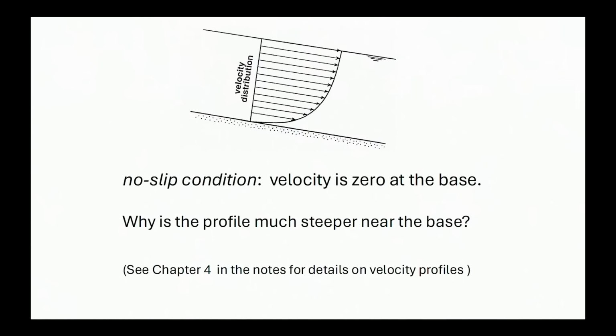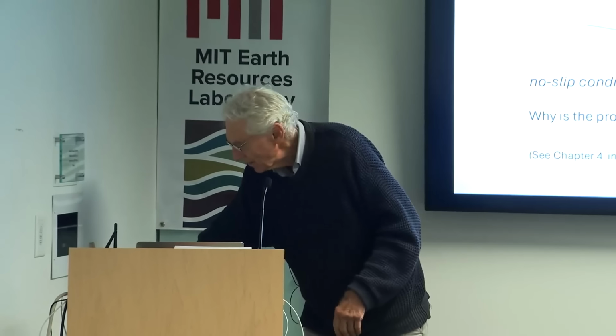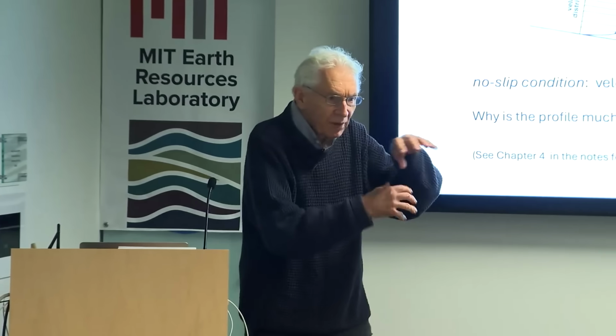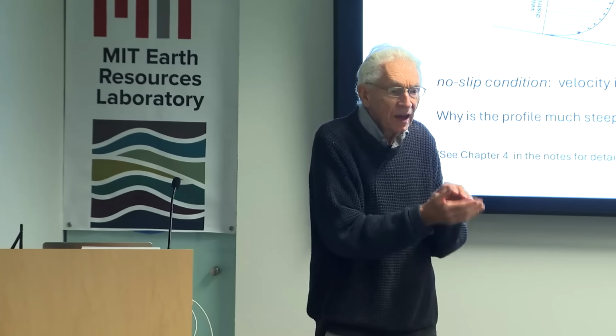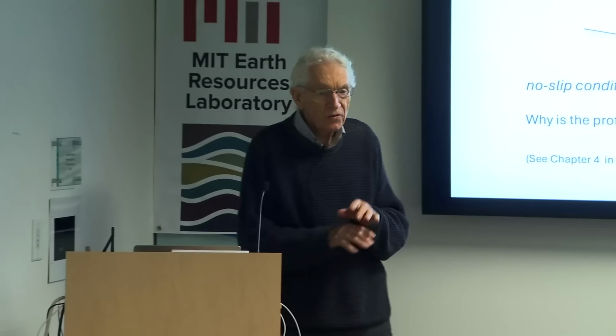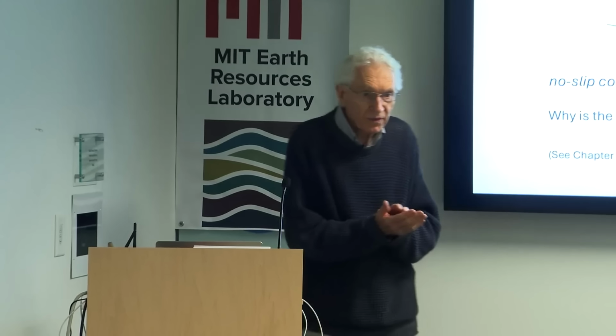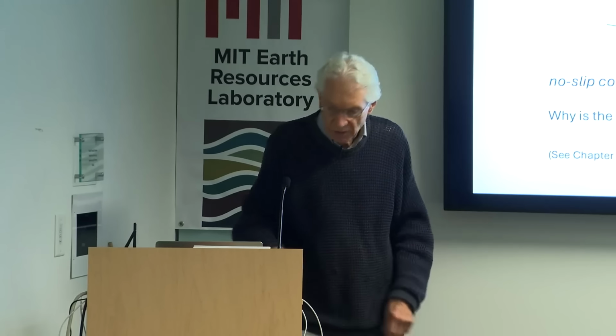It's a turbulent flow, and the turbulent eddies are doing their thing. But the closer you get to the bottom, the less possibility there is for the turbulence to exchange momentum vertically. And that goes to 0 at the boundary because the flow is always parallel to the boundary at the boundary, right? So over most of the flow, there's very effective mixing back and forth, eddies exchanging positions, and evening out the flow structure, the velocity. Whereas you go down near the bottom and the turbulence becomes imperceptible. And so the flow has a very steep gradient right near the boundary.